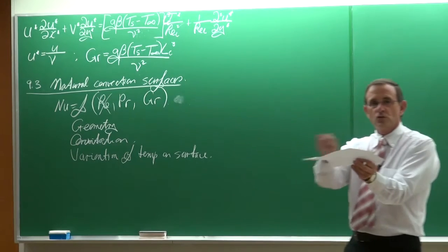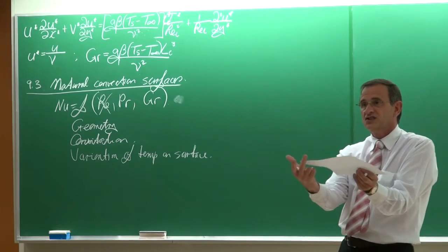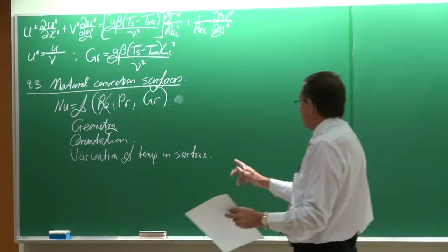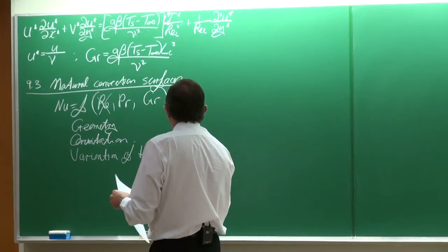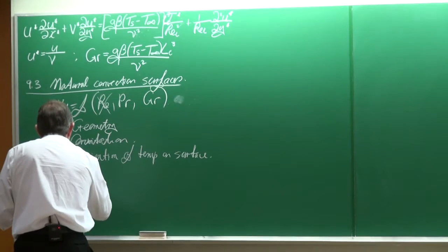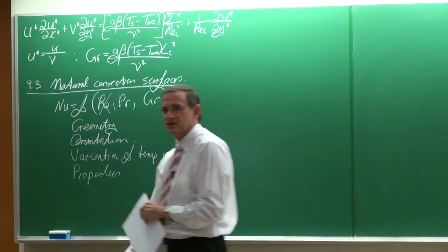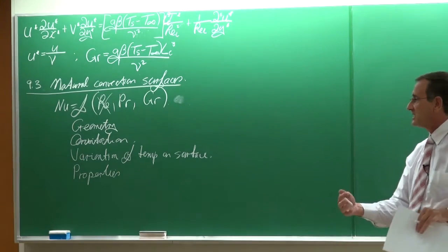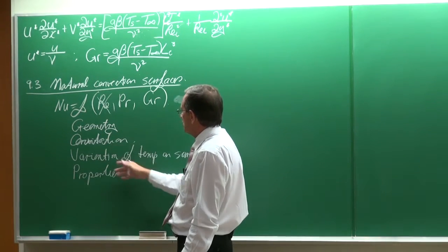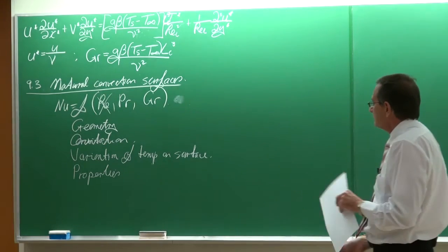So is it a surface where it's a constant wall temperature, or is it a surface where there's a constant heat flux, or are there changes in the temperature? That plays a role. And specifically this temperature influences the properties, the thermophysical properties, the thermal conductivity, the viscosities, etc. All of that is specifically being influenced by this temperature or the representative temperature that we should use.